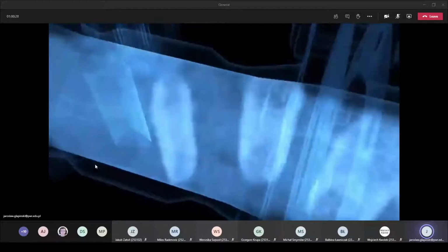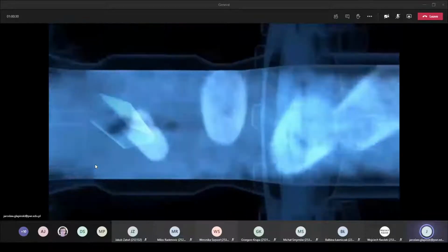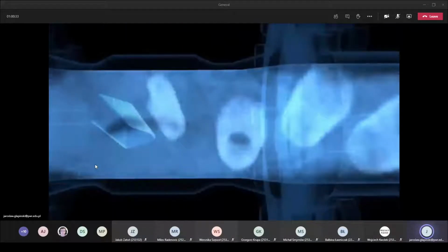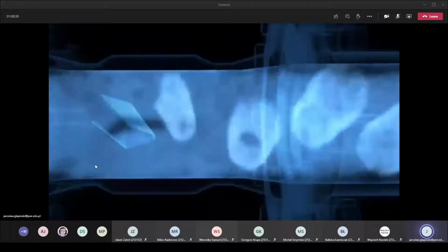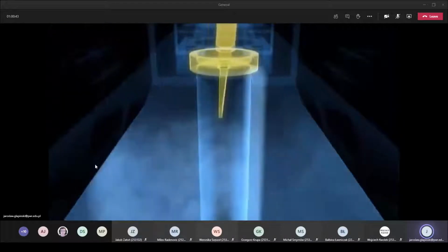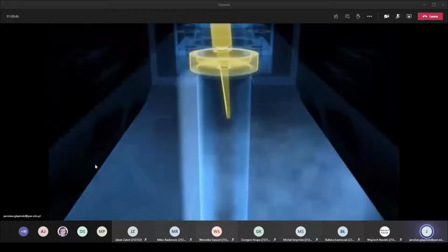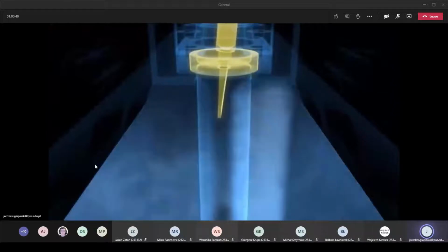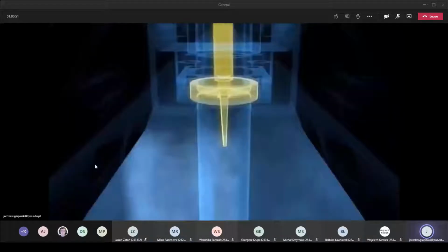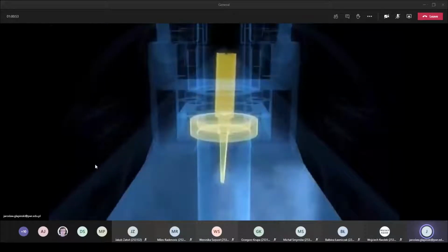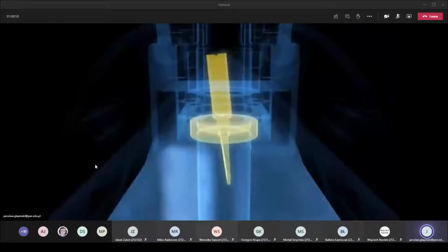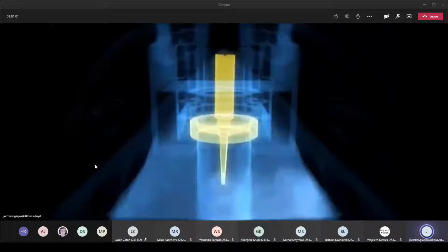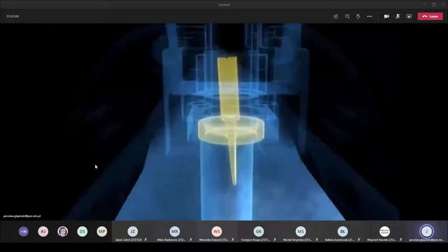Zones of high or low pressure now appear downstream and thus create a phenomenon that is known as the Kármán vortex street. These differences in pressure exactly match the frequency of the passing vortices and are precisely registered by the mechanical sensor, shown here in slow motion. This sensor is unique because it's inherently so well balanced that pipe-borne vibrations of up to 1 G, pressure surges, and temperature shocks have no effect whatsoever on the measurement.